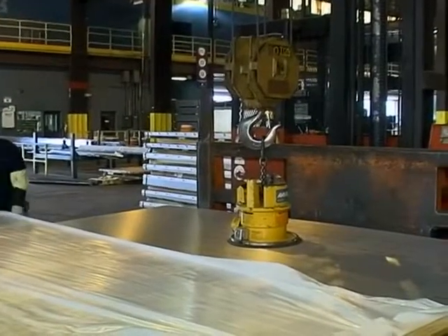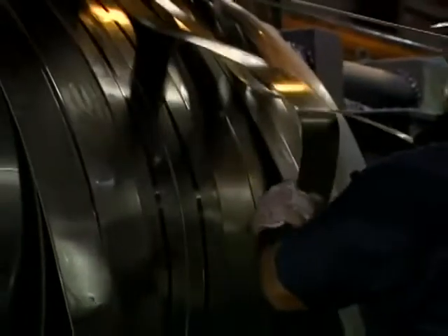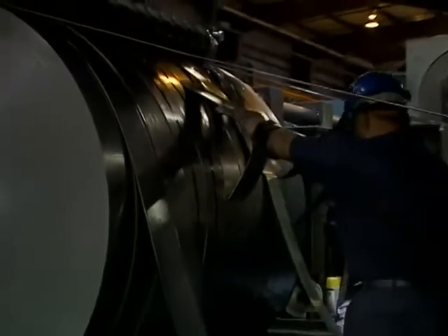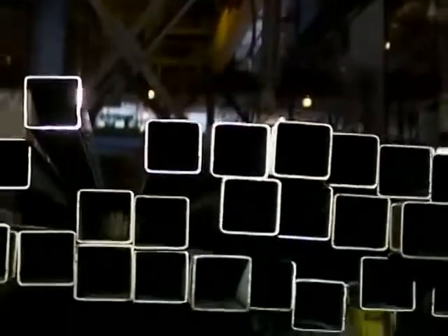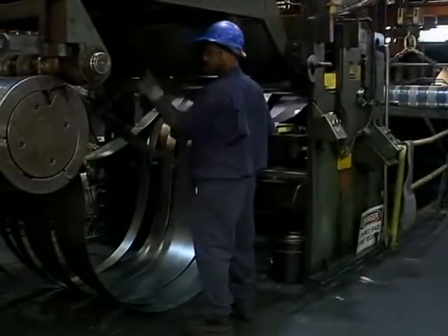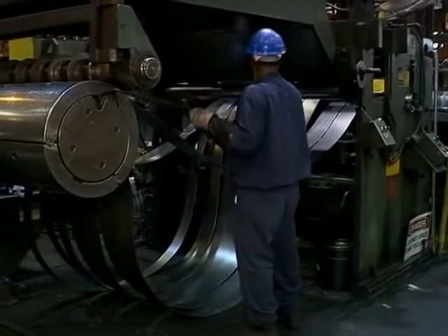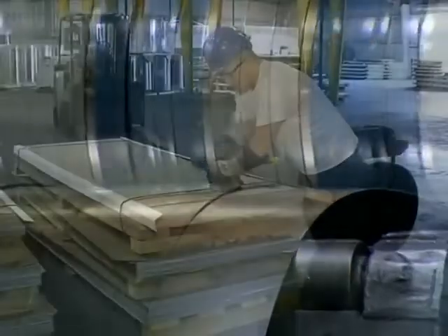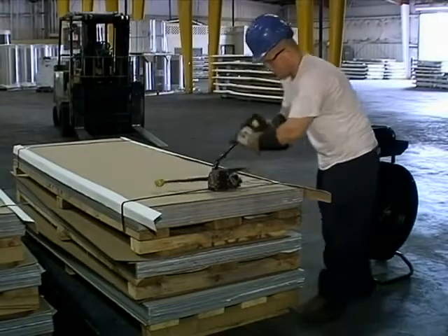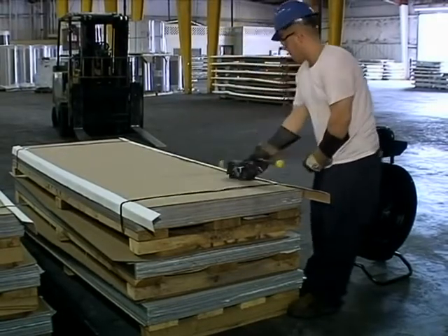Although the number one focus is to remove or minimize laceration risks through engineering controls, it is not possible to remove all hazards from operations. Because of the products you handle, there are several jobs that are identified as laceration risks. When handling sheet product or processing coil material, there is a laceration risk if accidental contact happens with the sheet's razor edge. The use of steel banding is another cause for concern. Typically, the edges have been rounded by the manufacturer of the banding, but a razor-sharp edge is created when the banding is cut on the end.